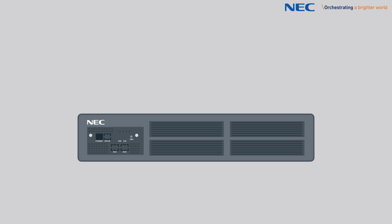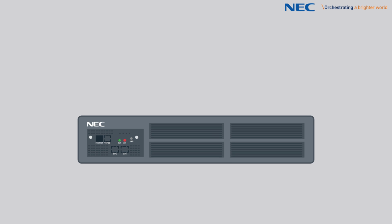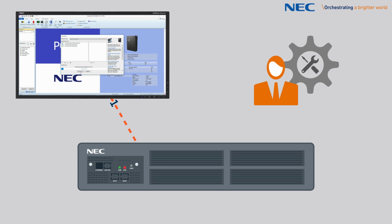To warm start the SL2100, turn the power switch on to the main chassis. When the system has completed reloading the system software, the Run LED will flash green on the CPU card and the system phones will display the time and date. Use SL2100 PC Pro to configure the system. See the separate video for PC Pro connection and operation.